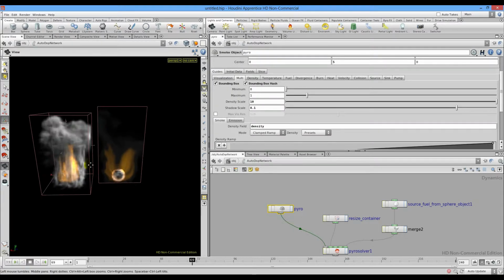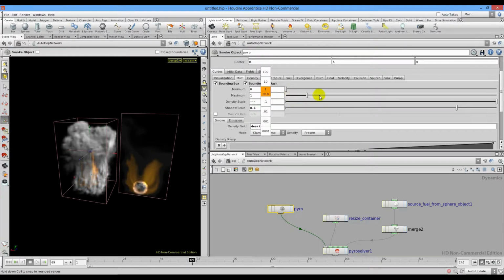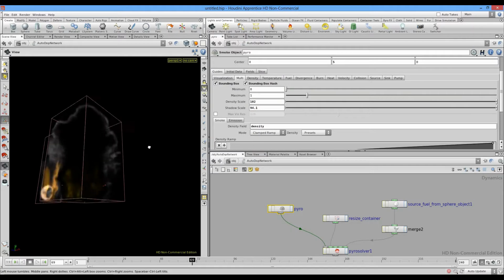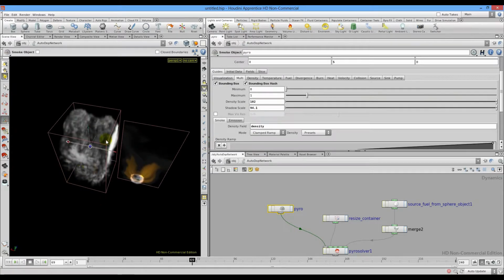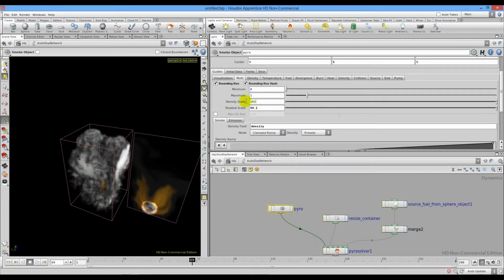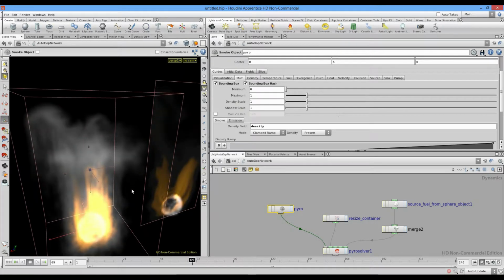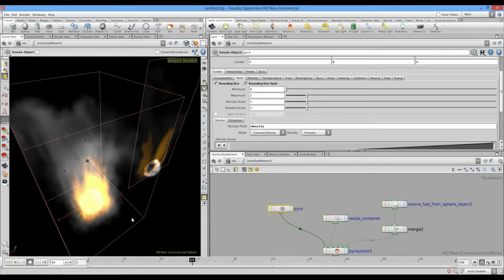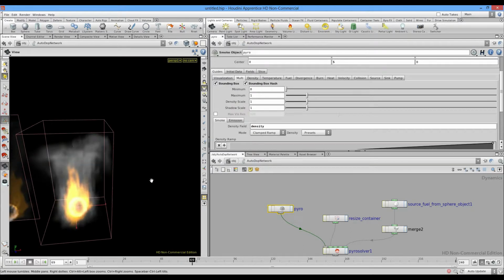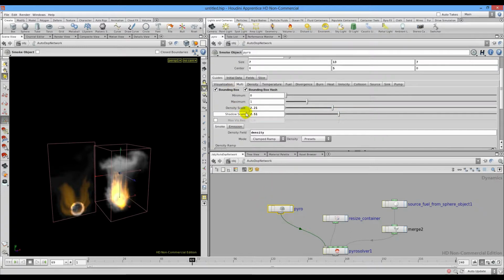So you see the light is affecting the viewport representation. If I set my densities too high and shadows too high, the simulation will look like this. It happens because the data is inside of this field, inside of this box, but on normal density and normal shadow scale, the data which is, for example, placed here is so settled that Houdini does not visualize it.